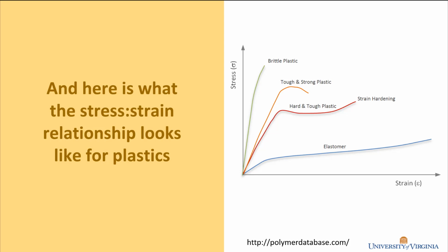Where it looks like all it has is that linear region from the plot for metals, from the stress strain curve for metals. And it turns out that polylactic acid, the type of plastic that we'll 3D print with, is a brittle plastic when it's below 45 degrees Celsius, which it's going to be once the part has been formed, right? And so that's another interesting reality, that stress strain curves are different for different temperatures, not that relevant for this project.